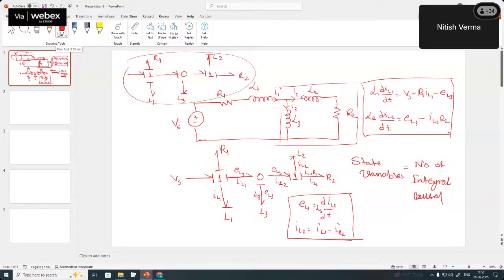Let's say I'm taking the example of a converter. So IL1 by D and IL2 by D, this is how I'm defining the transfer function. This is how I am designing the controller as per the transfer function to get the required phase margin. And this is how I'm controlling my IL1 current and IL2 current. So how to control the IL3 current if it is an algebraic equation, sir? By controlling IL1 and IL2, because IL3 is nothing but IL1 minus IL2.